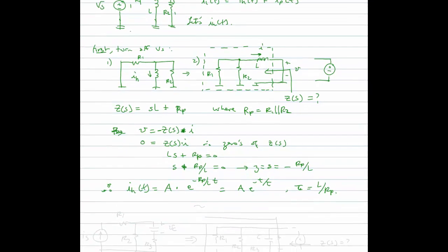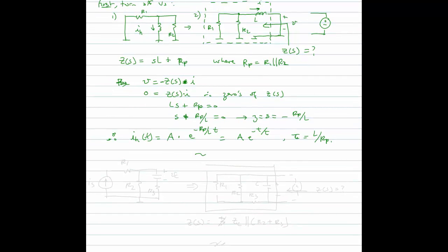And we can do the same thing if, let's say, we had a circuit like this, and it wouldn't matter what the source was over here, whether it was voltage or current. Let's go ahead and do current here. Now I say find the voltage here, find the homogeneous response. Well, all I would do is turn off this current source, if that's indeed a current source.